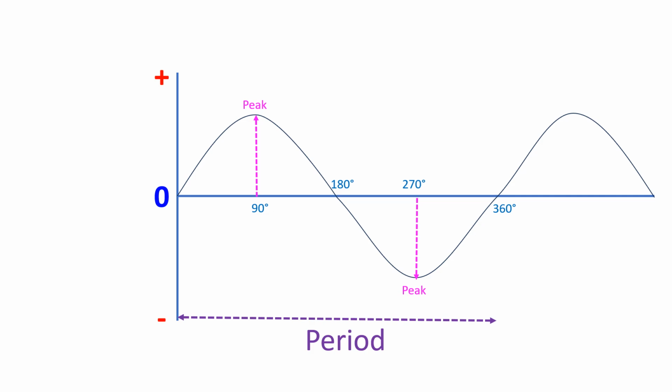We have seen that voltage and current values follow the sinusoidal pattern for an alternating current. Peak value is the highest positive or negative amplitude of the sine wave. Average value is the arithmetical average of all instantaneous values in a half cycle of the sinusoidal wave and will be 0.637 times the peak value. Obviously, the arithmetical mean of a full cycle will be 0 as the positive and negative values cancel out.